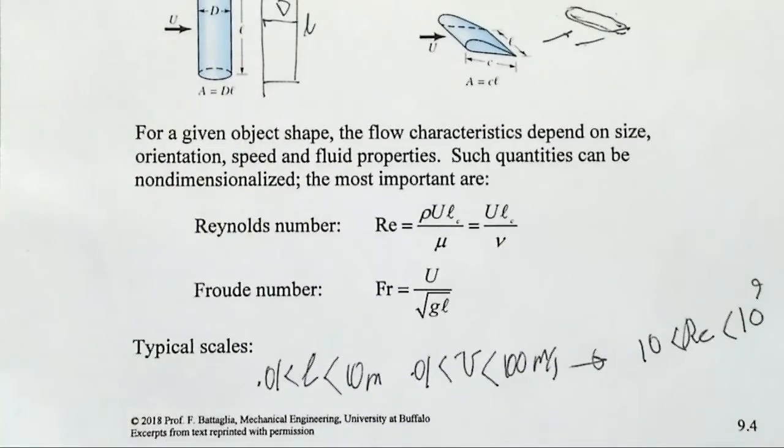So if you find out, for example, in any question, the Reynolds number based on the velocity that you found, or you did a calculation analysis and find the Reynolds number is 10 to the power of 12, you will find out somehow that you made a mistake. So you need to know what is, in general, the range for these, right? So it's going to be helpful.